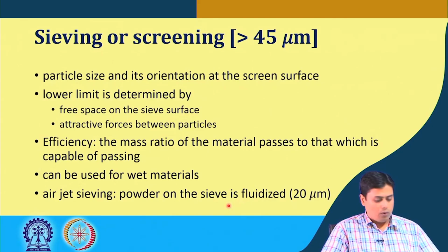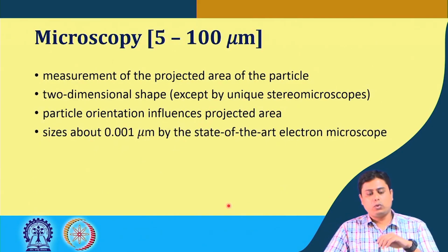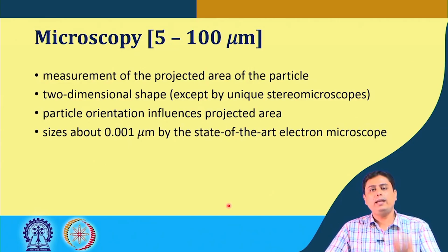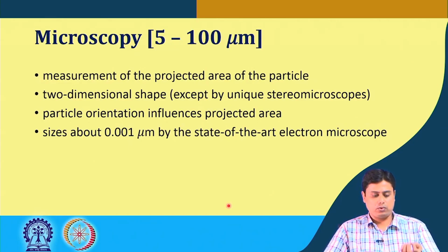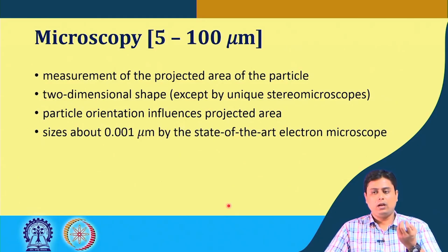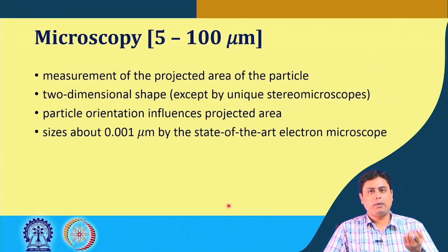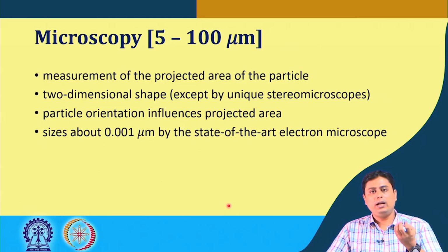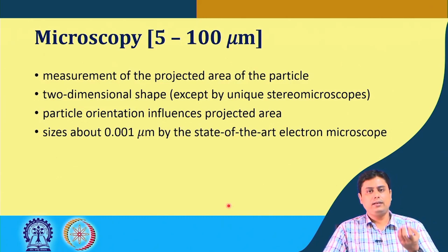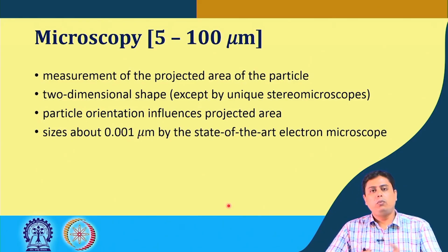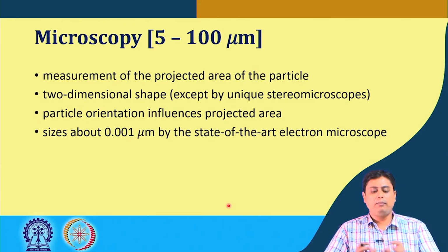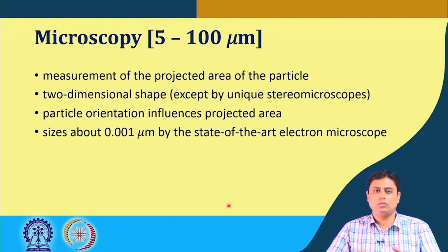Next, if we go for the microscopic method. In the microscopy method, you place a particle under an optical microscope. Here you can do it for a single particle, put it under an optical microscope and determine its size, or you can put several particles together under the microscope to have a size distribution.